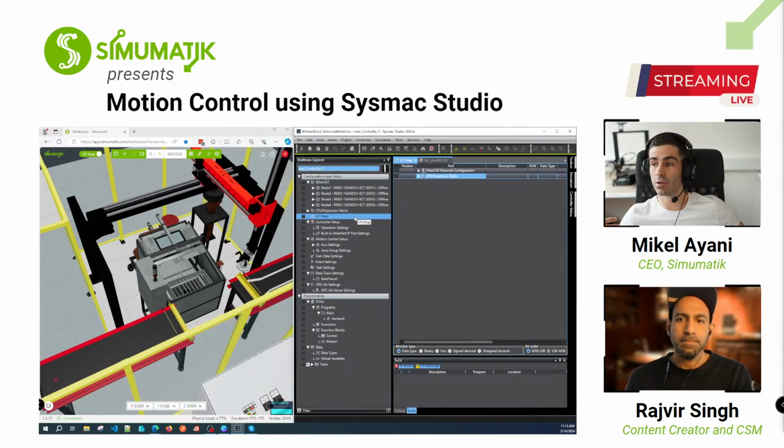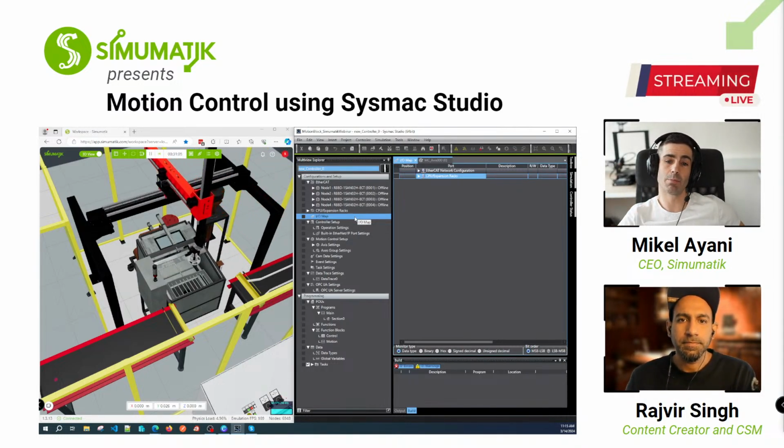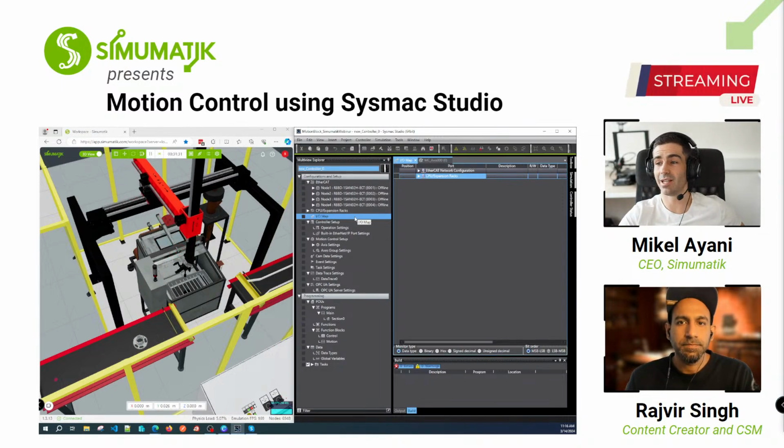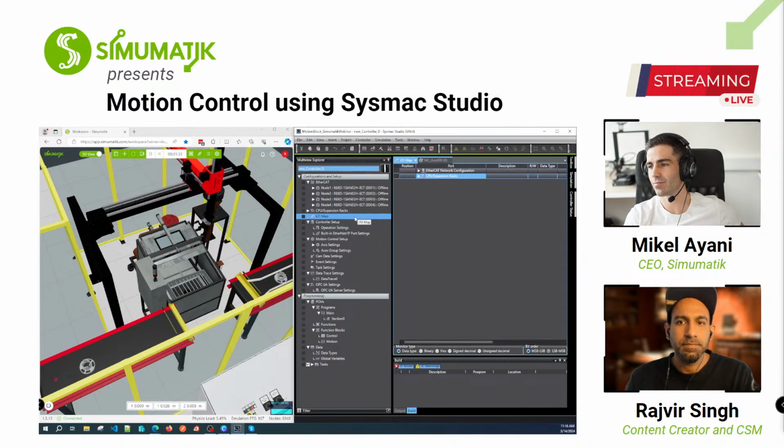Like in most, or I would say all, of the platforms we have been playing around with, when you run the PLC code in simulation mode, it happens like here. The EtherCAT or whatever is simulated, and the axes act like ideal axes. So basically, when you use the move absolute functions and so on, they will generate a trajectory, and the set point position and the actual position will be similar.